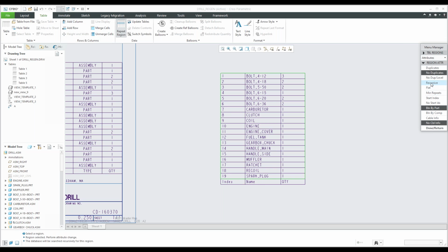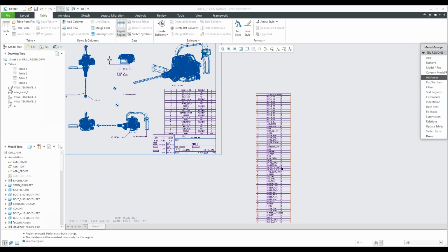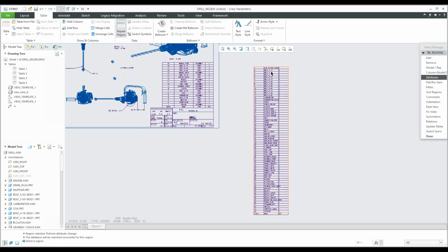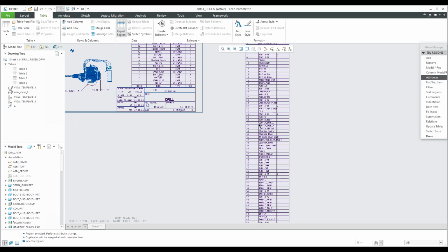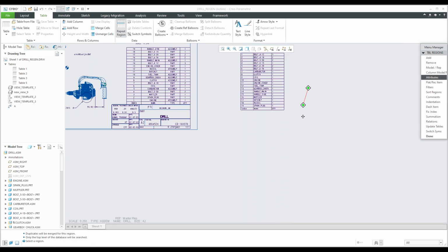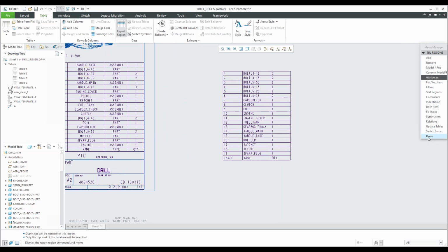And let's say I want that to be recursive. That's giving everything now, maybe not great. Use no duplicate per level. And let's change that back to no duplicates. And do we want it flat? Let's say flat and see what happens. There we go, that's what we want. Nice, compact bill of materials.